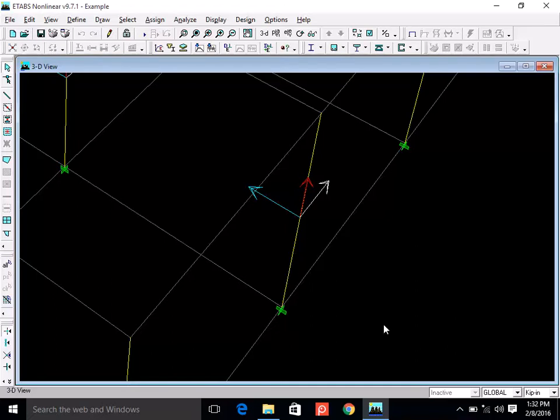Now bending moment. Again, because you have gravity loads on the beams mostly, bending moment is either like this in the midspan or it's like this on the support. Both of them are about which axis? It is about axis 3. So gravity loads are producing bending moment about axis number 3, and beams mostly have gravity loads. That's why M3 is important.